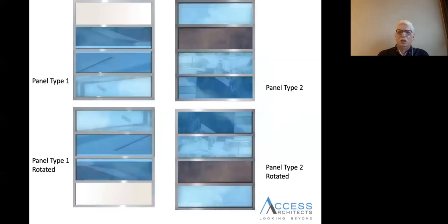What also we did was converted in the whole building only two patterns. So they were standardized glass. It's easier that if there is a breakage, you are able to replace it well. Also, you are able to standardize everything for execution. So what we did was create two, panel type 1, panel type 2, and they were used upside down or straight in different location to ensure that you get a design intent which is different. At the same time, you are able to get the intent of least amount of heat gain wherever you want.